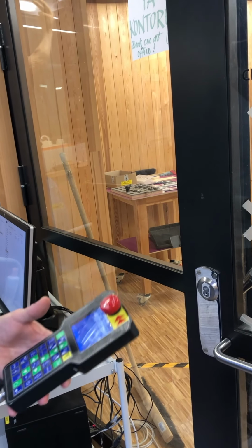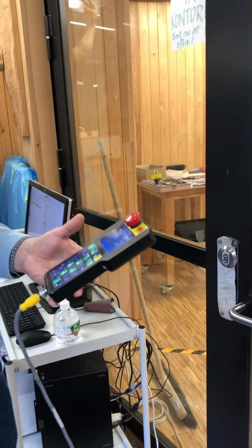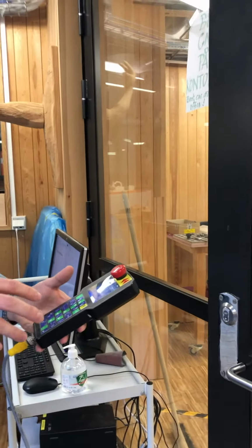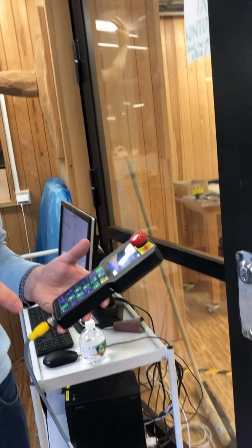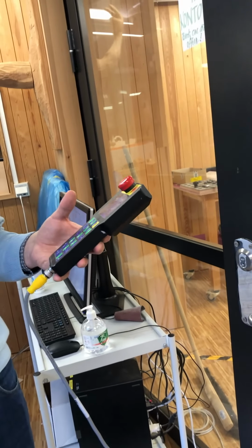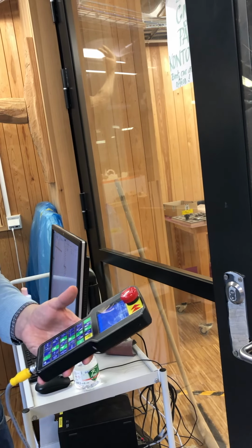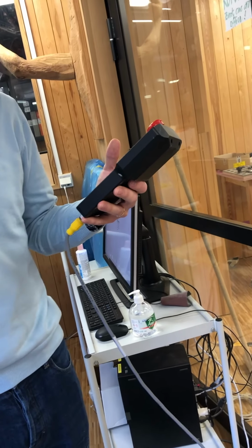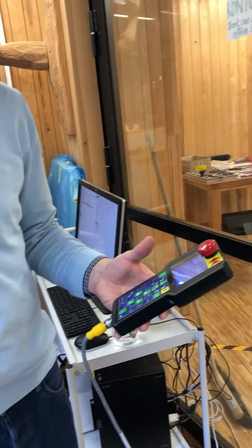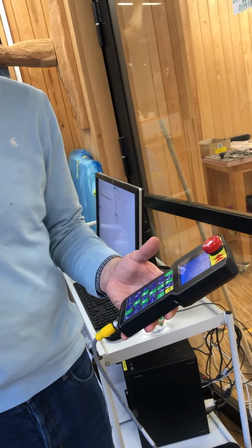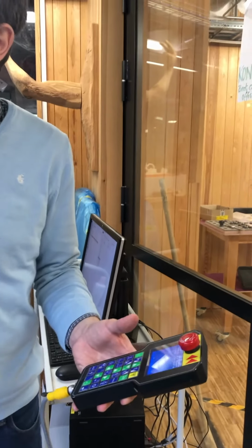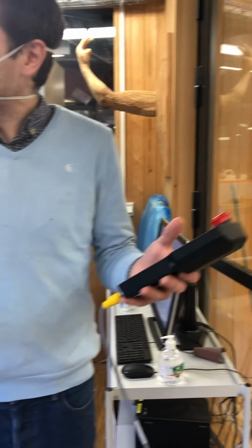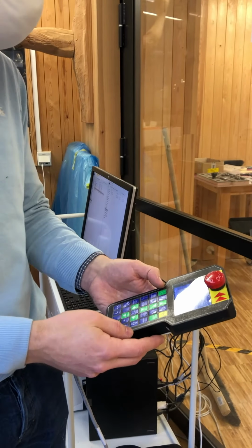a guideline when it's wood, now it's a very soft material, styrofoam, but if it's wood, it should always be wood chips, not sawdust. Because if it's sawdust, then it's going too fast. The spindle is of too high RPM, the chip load is too little. That will make excess temperature. It will increase the temperature. You will have a risk of fire. Yeah, you don't want that at all, because it's a spindle, a piece of carbide steel moving around its own axis at 18,000 rotations per minute. That's friction if not handled carefully.